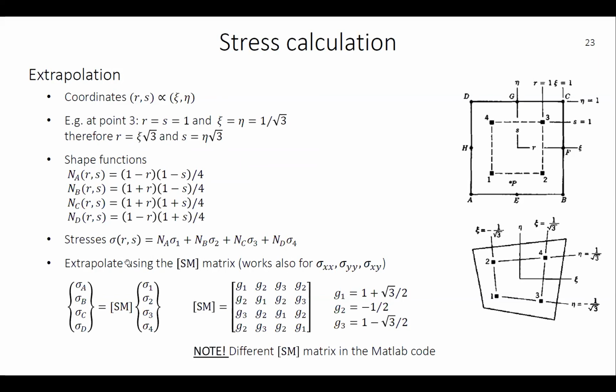So the stresses at any given point R and S in this domain are a linear combination of the shape functions defined at points A, B, C, and D. And this can be rearranged into a matrix form, the stress matrix, which for a 4-noded plane element is a 4x4 matrix having this format.